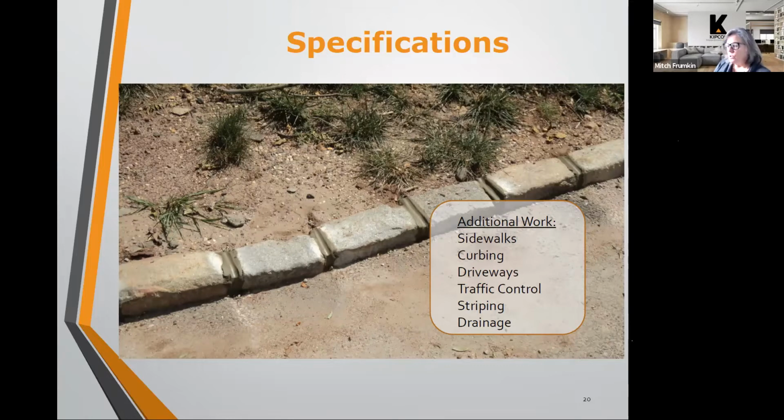So it's very important to stage any multiple projects that you have so that the roadways are done last. When they redo driveways, you don't have the same layers that you do on a roadway. Typically, when you do a driveway, you've only got a couple of inches of asphalt there, so you have to demolish and reconstruct the driveway.